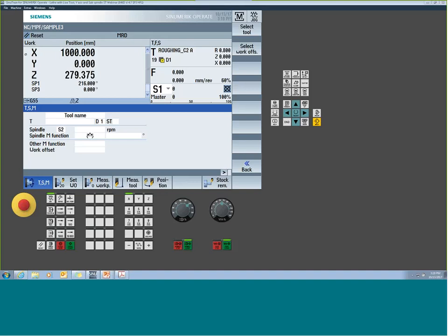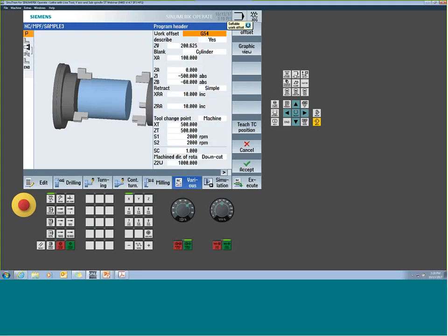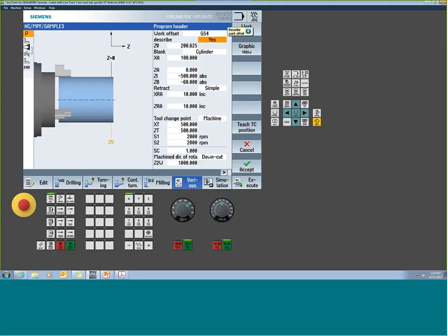Is it possible to use the sub spindle alone, like a single spindle? If yes, which setting do we need to activate? Oh, okay. So if I read this properly, you want to be able to just run the sub spindle as opposed to running the main. It's really just using the work offset that's mirrored for that. Some of them give me the ability of telling it which spindle I'm working on here. In this case, you would just pick the appropriate work offset, and it's automatically going to drive to that sub spindle. So yes, you can use the sub spindle by itself.